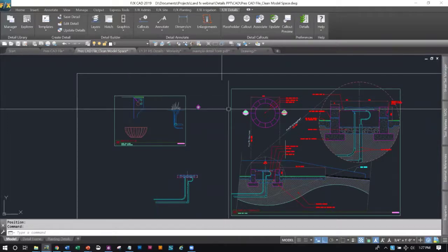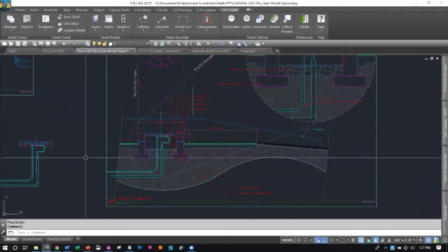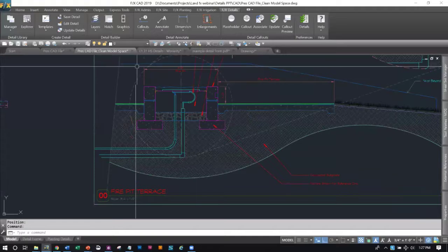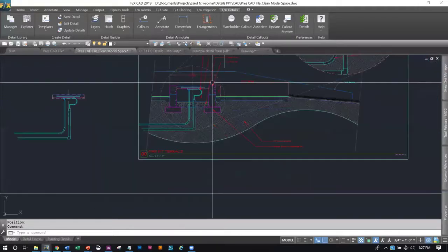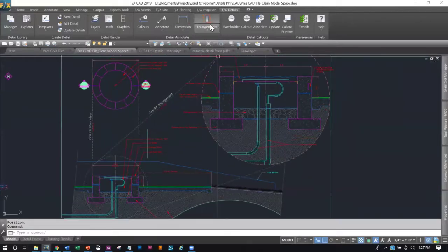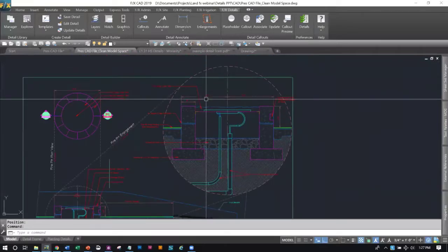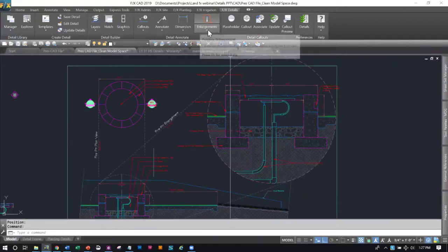Another feature of building the detail: you'll start out building your detail at a smaller scale, say a 3/4 inch detail, but you need to add some additional notes and information. They have a great enlargement tool, which is great for blowing up the size of the detail. So this detail has been enlarged. Looks like I enlarged it to 1 inch equals 1 foot within their system.